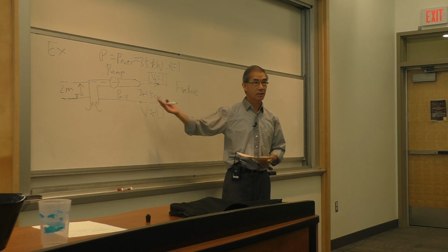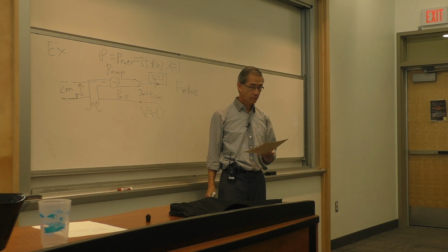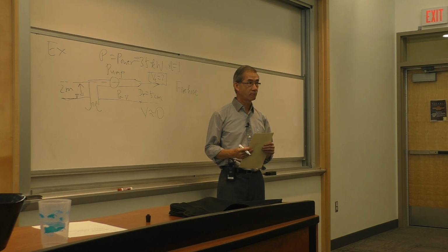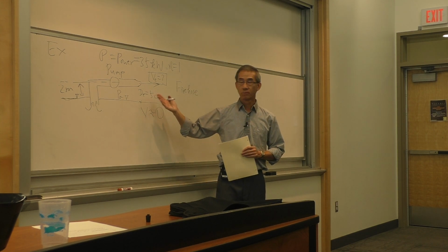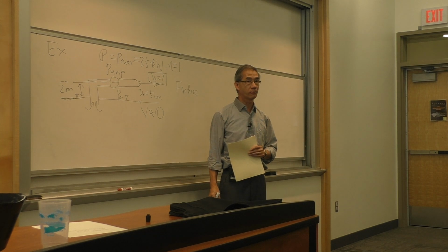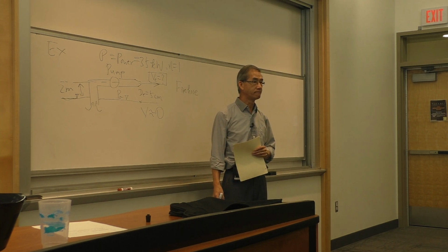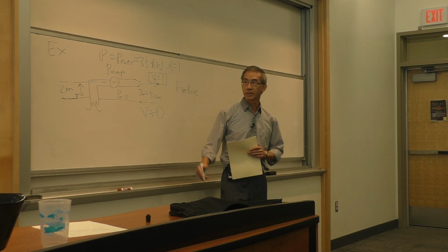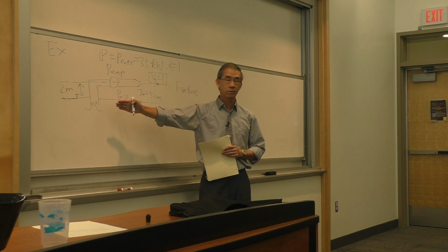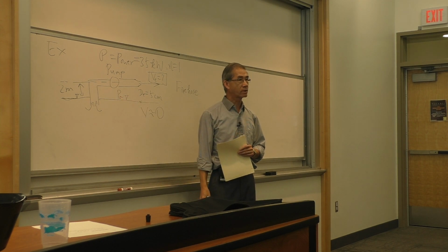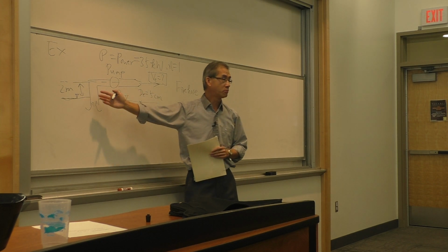Viscous, now first of all, I didn't tell you this is a frictionless problem, right? And then, what else? You cannot use Bernoulli for a second reason. The impeller in the pump is chopping up the streamline. You can never follow a streamline, right? So the physics is I'm adding energy to the water to overcome what? To overcome what? Gravity or 2 meter, what else?